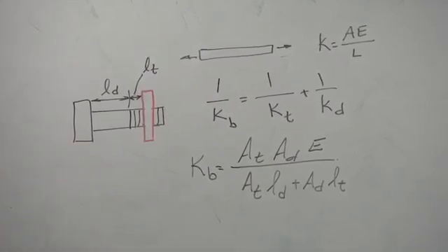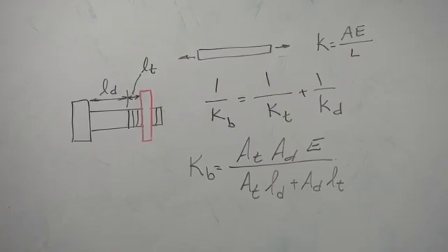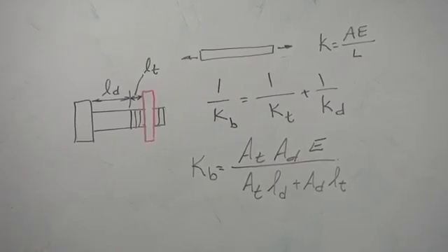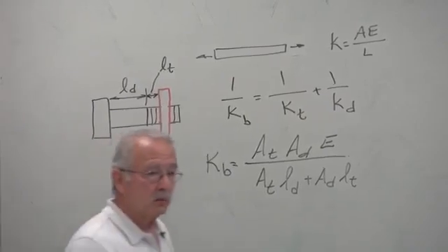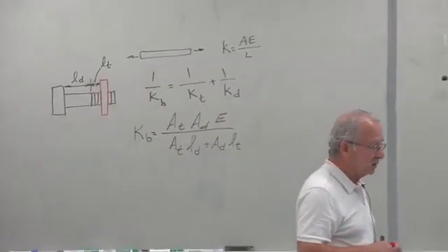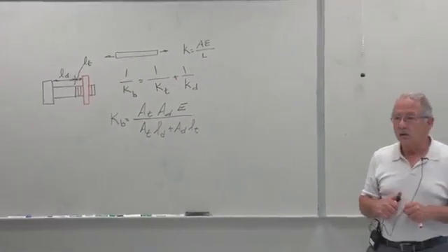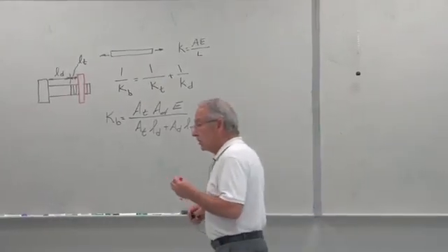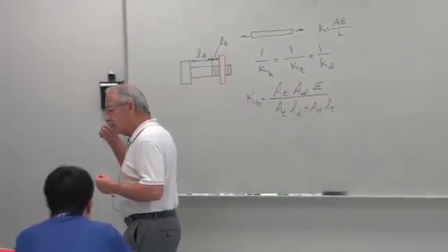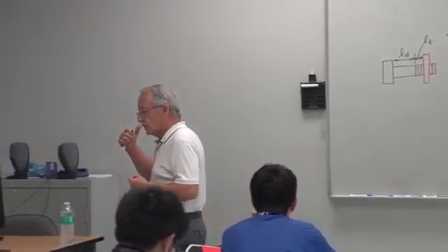So that's where we were last time. In order to be able to analyze the stresses in the bolt and or the member once we tighten the bolt, we need to take into consideration not only the stiffness of the bolt, but also that of the member.